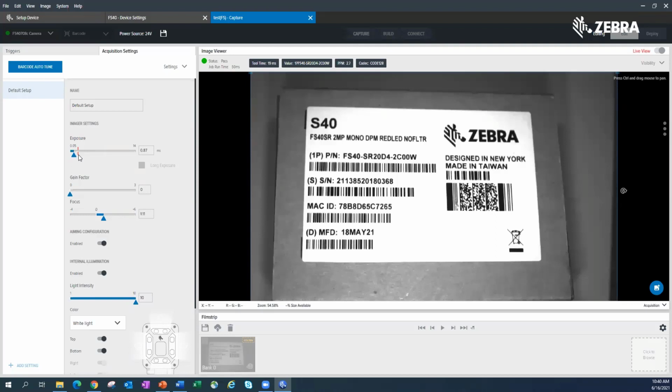Basically, once you go over that line, you need to use some external light, or you start introducing ambient light into the frame to add more light. For barcoding situations where you're going fast, on a conveyor belt, or somebody's moving a box underneath it, you want to have short exposure times, right? The internal light is designed to be very bright, very powerful, and very short. We're overdriving these, giving you the maximum amount of light at a very low shutter speed.